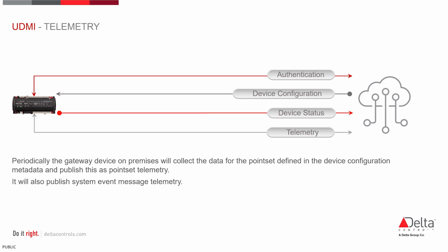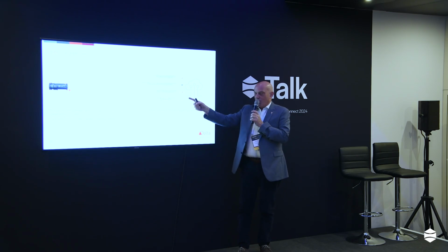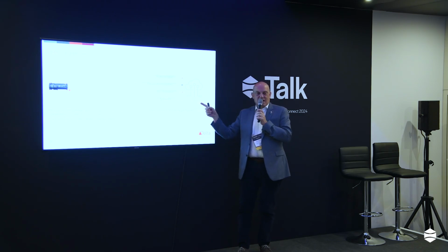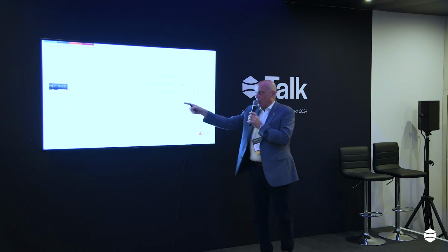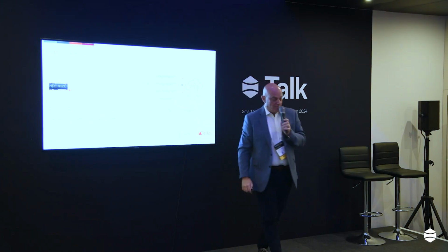Once the device is configured, it then sends status back. The status goes periodically, so the cloud knows the device is there, it knows what version it is, various parameters that are defined within UDMI, and subsequently the telemetry, which is the important bit. This is the readings from the values, the statuses, the set points, all come out of the controller, published periodically to the cloud into the data lake.